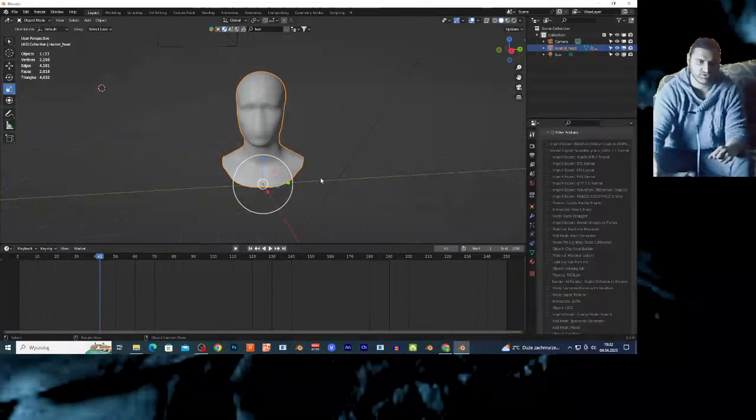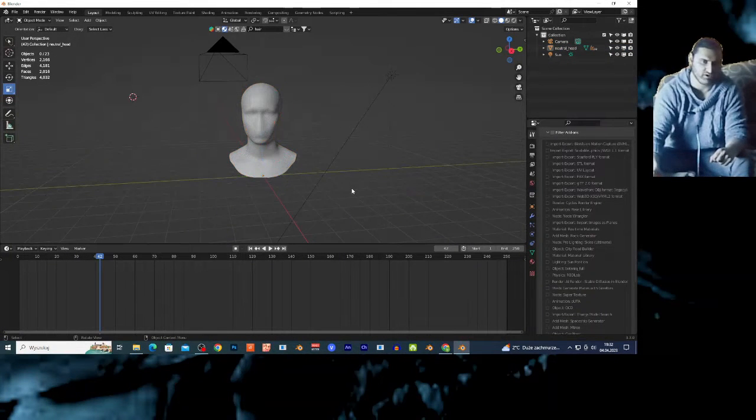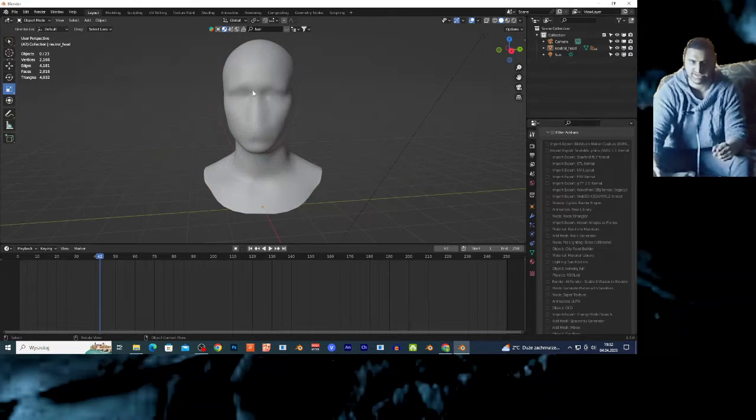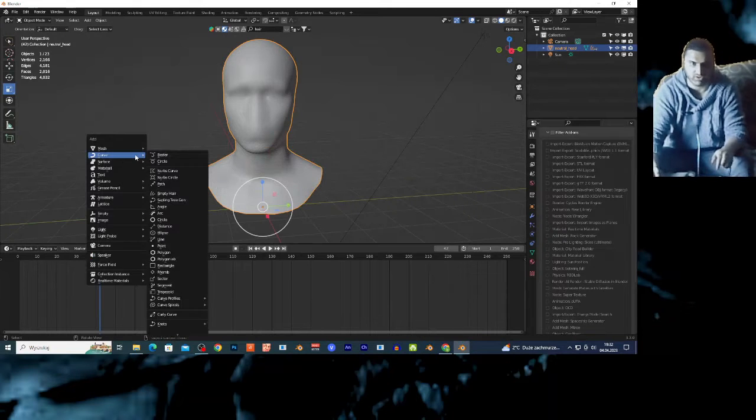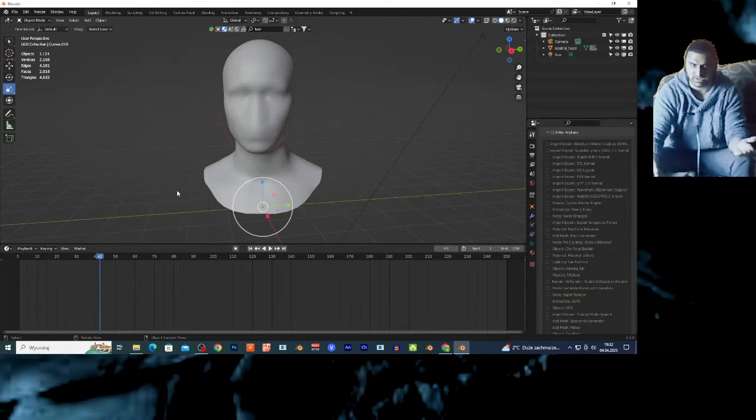What's up guys, today I'm gonna show you how you can add hair to your 3D model in Blender. So, to add hair, select the 3D model, Shift A on the curve, add empty hair. Nothing's happened, you must change this from object mode to sculpt mode.